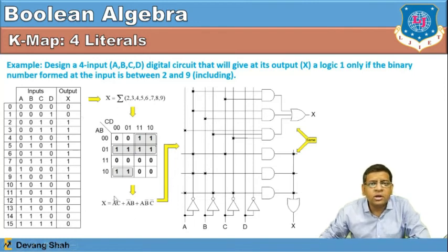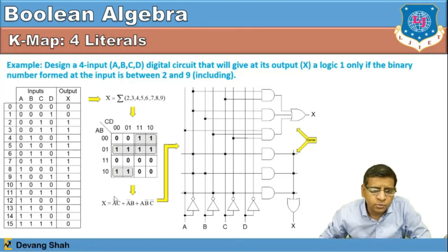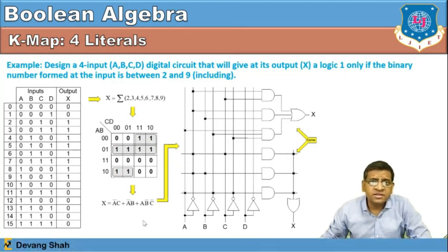So you use your K map, put the corresponding ones in the specific blocks of A, B, C, D with the sequence. Is a group of 16 ones possible? No. Then go for 8 ones in a group. Is it possible? If yes, then go for it. If no, then 4 ones is possible. Yes, here 4 ones are possible, in two groups, having A bar into C plus A bar into B, where A bar into C is the first two rows and last two columns, right? In the same way you have A bar into B, it's completely the second row, so there is no importance of the columns here. That's why this term is A bar into B.